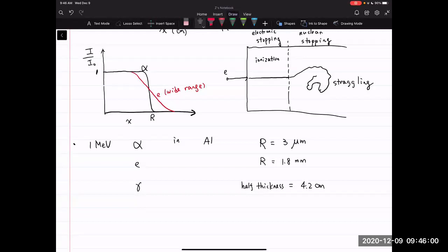For the thermal neutron, the cross section is almost 0. So aluminum is almost transparent to neutrons. There's really no half thickness. Neutrons can go through aluminum without seeing anything. They can go much deeper than gamma. That is why for neutron facilities, we use aluminum to construct the instrument. Even if we use very thick aluminum, to neutrons it is just transparent.